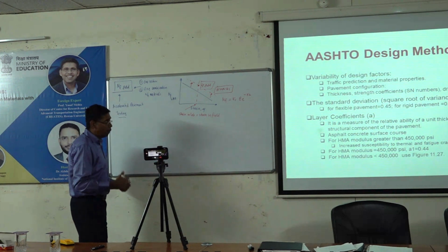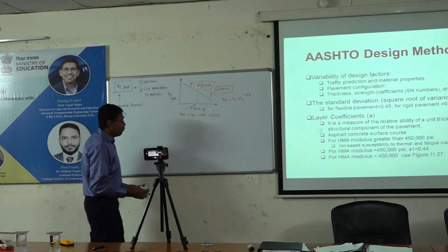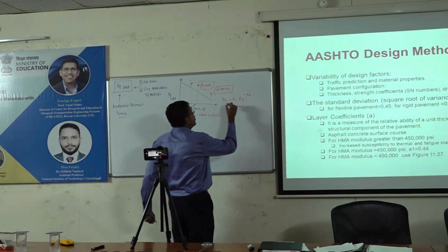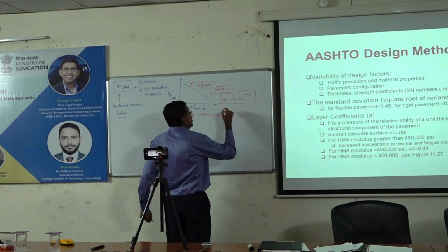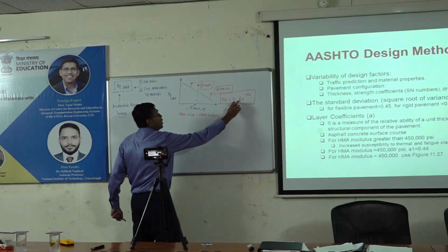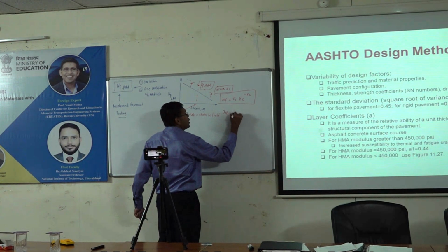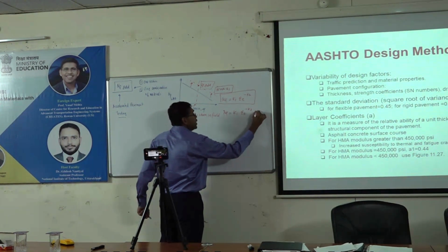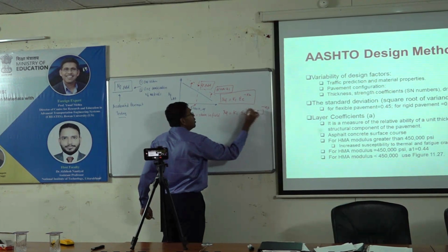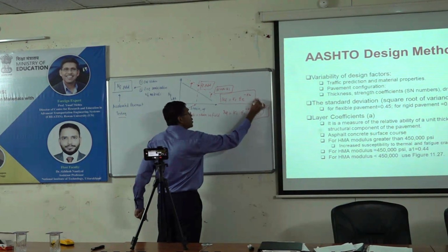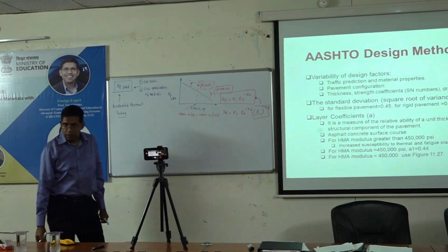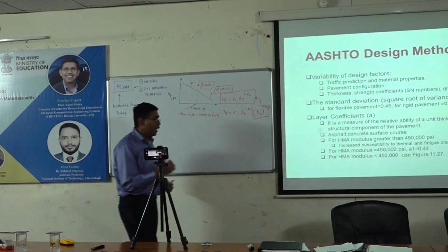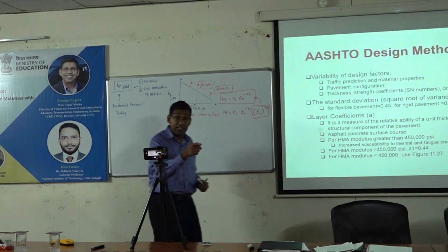Now when you do multiple tests of different moduli, this is already calibrated for a given mix, for a given E. And then all you are doing is adding this coefficient to this model. Does that make sense? So you are only calibrating on the strain equation, and then you are adding it to the modulus equation. That answers the first question.